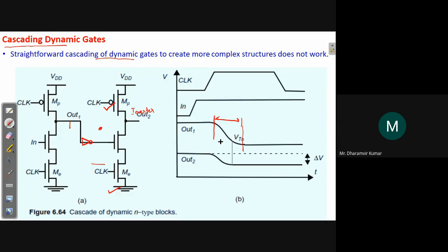Okay, and this is the threshold level. So during this time, this NMOS will take this part as logic high, logic 1, because the value is still above its threshold value. So by inserting an inverter here, for this duration of time, this 1 will actually be served as 0 to this NMOS, and this will remain off. And if this is off, the output 2 charge will not decrease, and it will be maintained at this level.